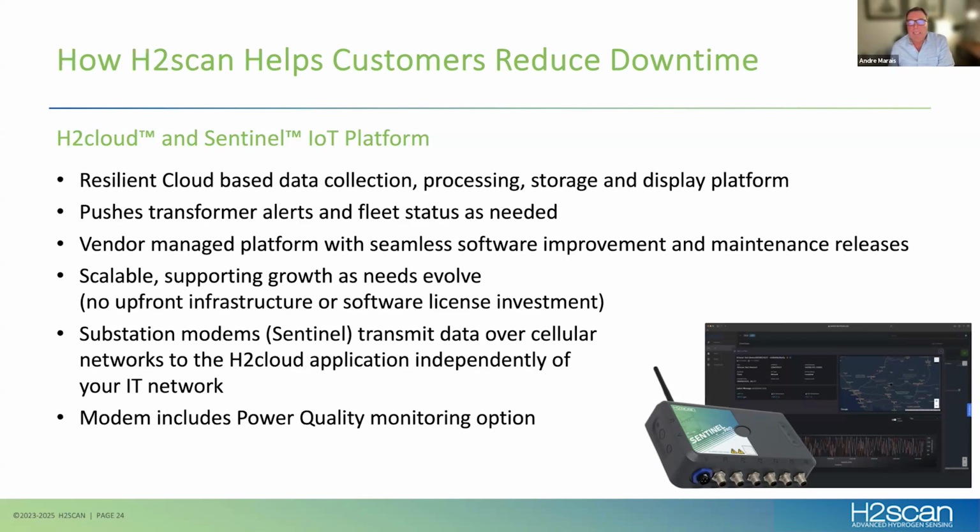We are adding the BACnet protocol to that product. It could also be added to this platform because the protocols are so ubiquitous. The estimated target date for BACnet is probably around July, August, but as of today we don't have that. We do have a mechanism to convert the hydrogen levels to analog 4 to 20 milliamps, if that's required, to help in the interim.